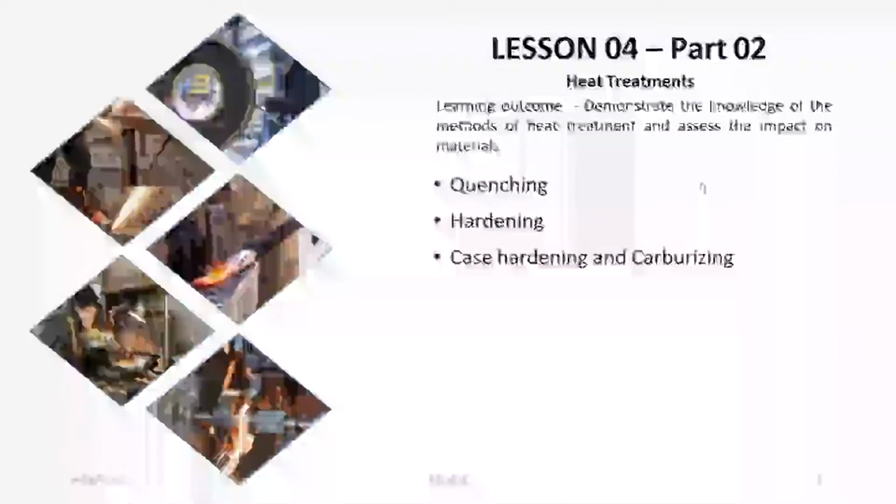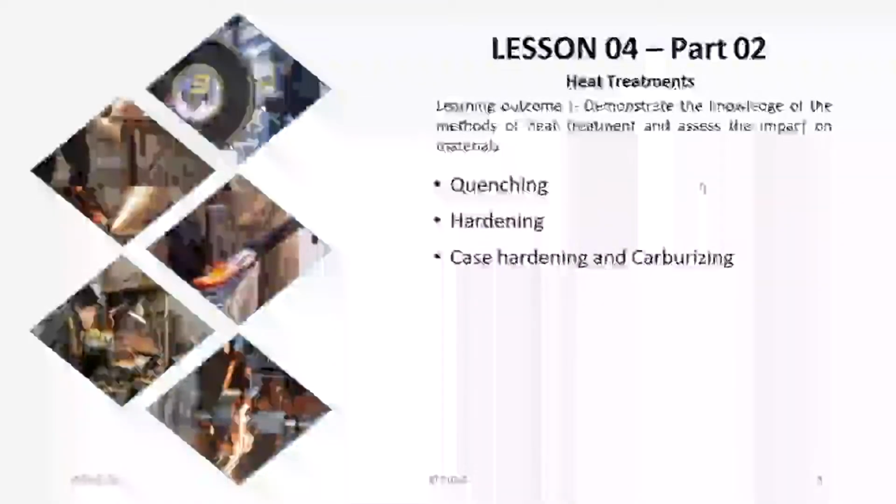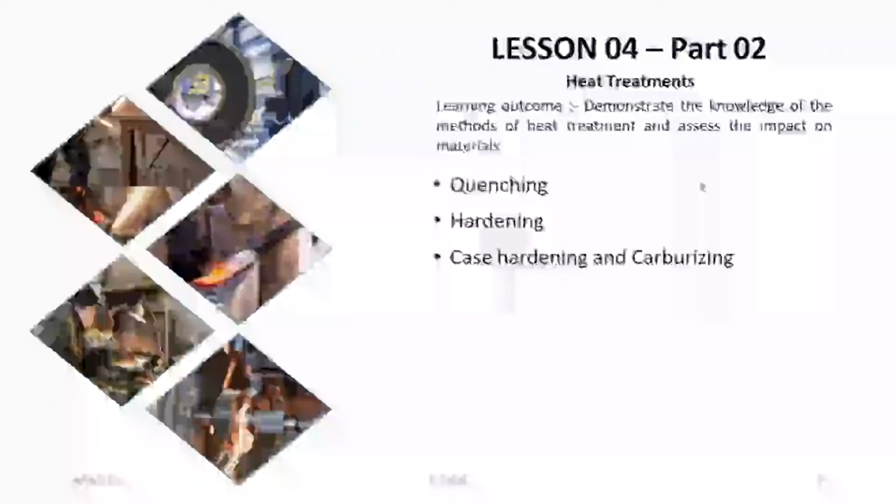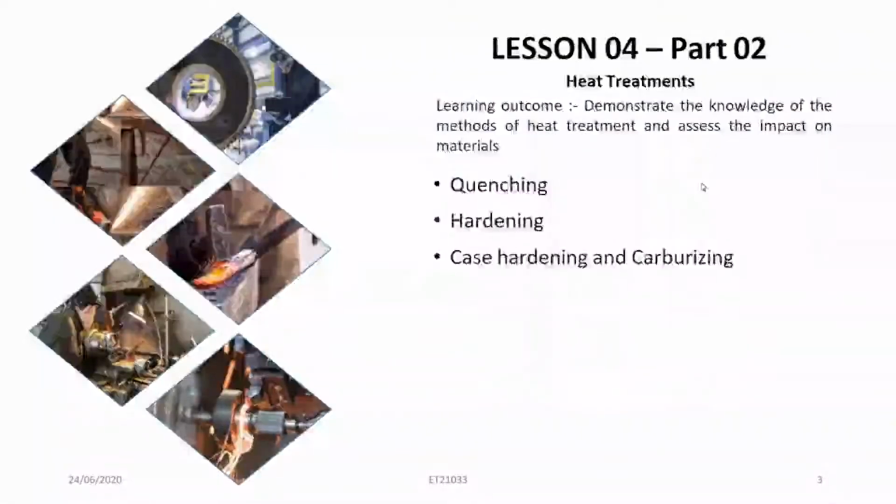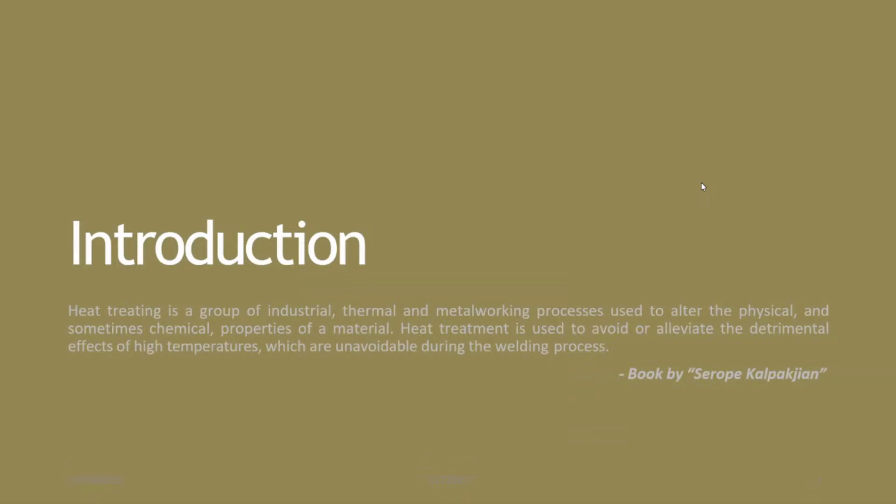Under this lesson, you have to identify the right heat treatment route for a job and explain the trade-offs. If a part fails by wear, you may chase surface hardness. If it cracks in service, you may need a different temper or a case hardening part that introduces beneficial compressive stress at the surface. So, a simple introduction.